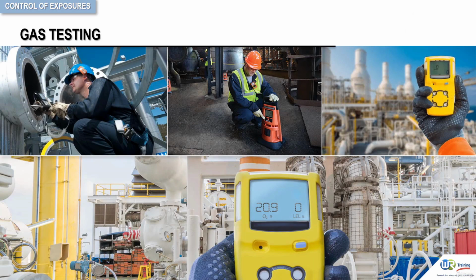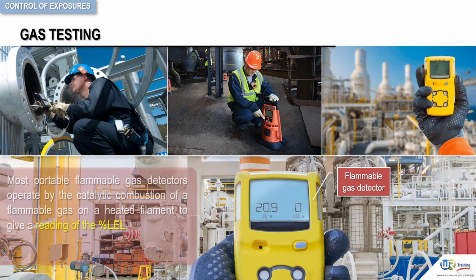Gas testing is important when personnel are required to work in areas where exposure to hazardous substances is a possibility. Inadequate or improper gas testing can be a cause of fatal accidents because many people do not understand the basic working principle of flammable gas detectors. Most portable flammable gas detectors operate by the catalytic combustion of a flammable gas on a heated filament, usually platinum, to give a reading of the percentage of LEL. Accordingly, there must be approximately 21% oxygen in the sample to give accurate readings.